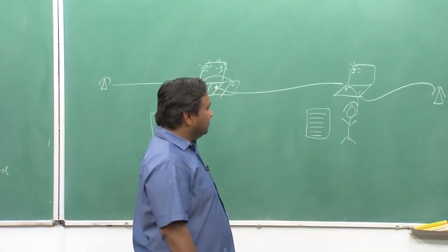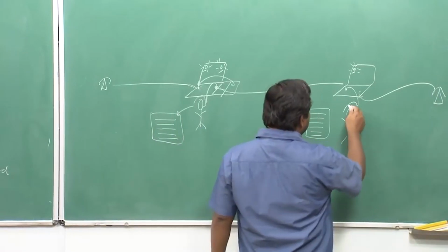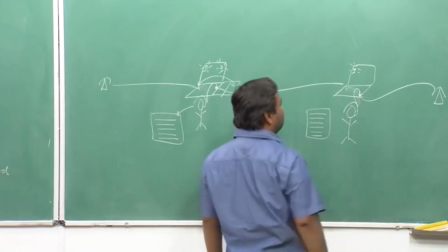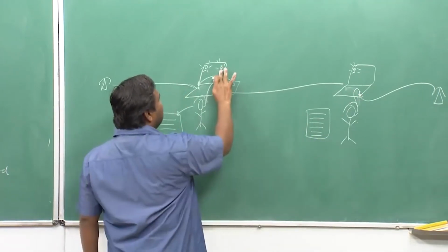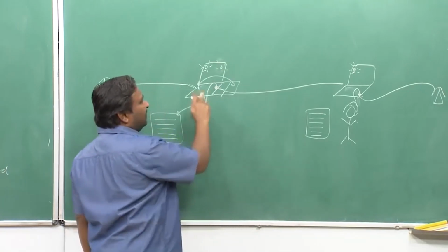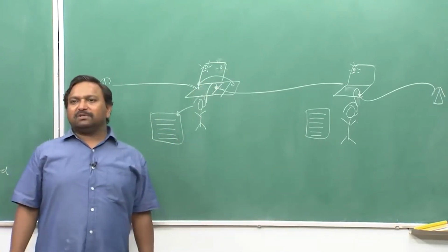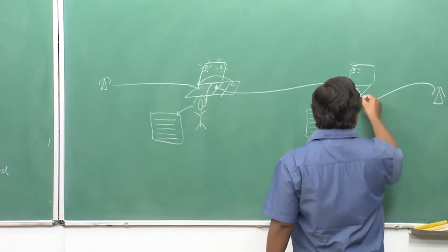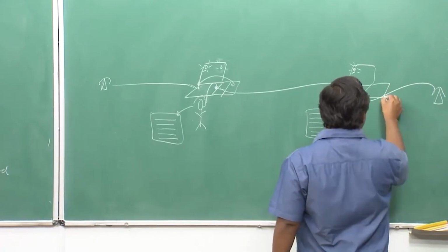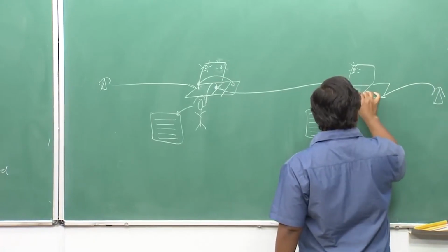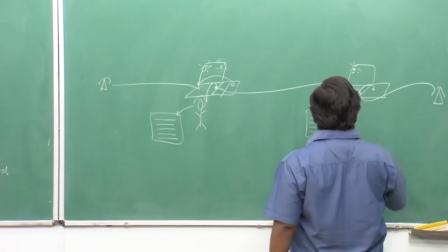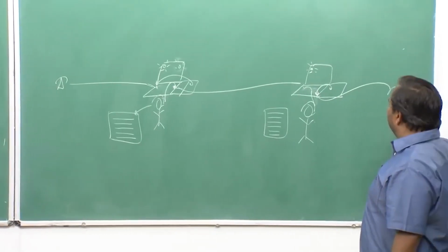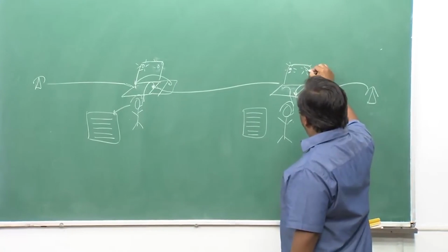So what will be done is, this will take out this headset and connect here. So this light is off now. Once this light is off, this operator knows that the call is currently in the process of being set up. So she has to wait till this light comes back, and then first of all before connecting this, she will connect the ringing source so that this phone will ring, ringing current. Once the handset is lifted up, the light will glow.